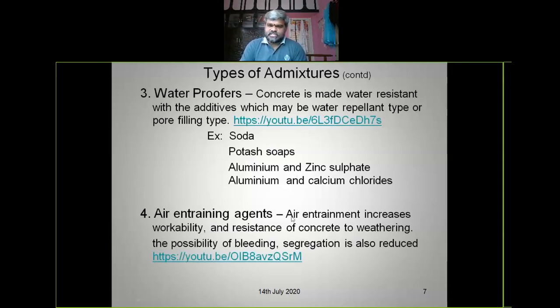So air entraining agents. The air entrainment increases workability and resistance of concrete to weathering. The possibility of bleeding and segregation is also reduced.